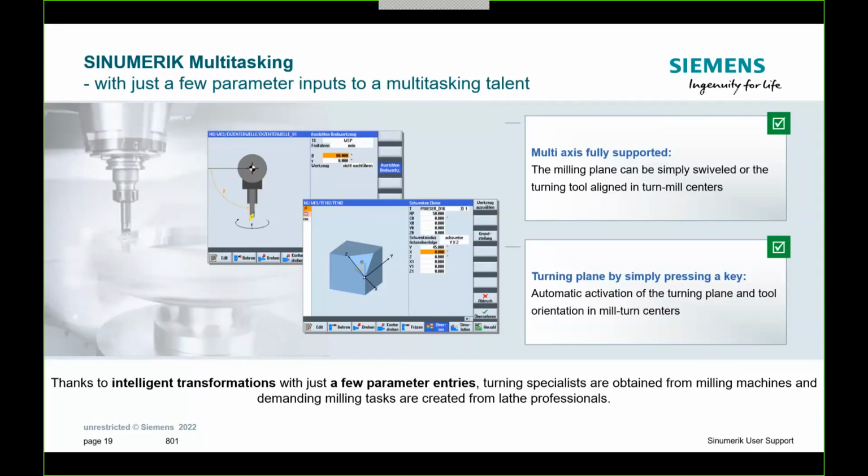And that's where you have to get your head around when you're doing these rotations. Don't think about the part turning. Think about I'm rotating the tool to the part. And then everything starts to make sense because anytime I turn that tool, I'm switching the coordinate system. And you'll see as we move forward how that works.